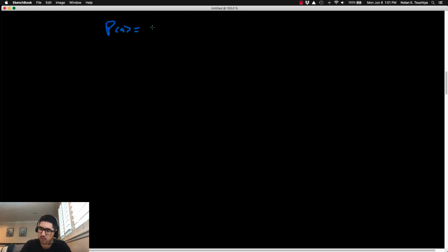And I can give you an example of what that looks like here. So here's some transfer function denominator. Right? This is one way to write a system with complex poles. If this were the denominator, I would have poles at minus sigma plus or minus j omega, so a pair of complex poles.